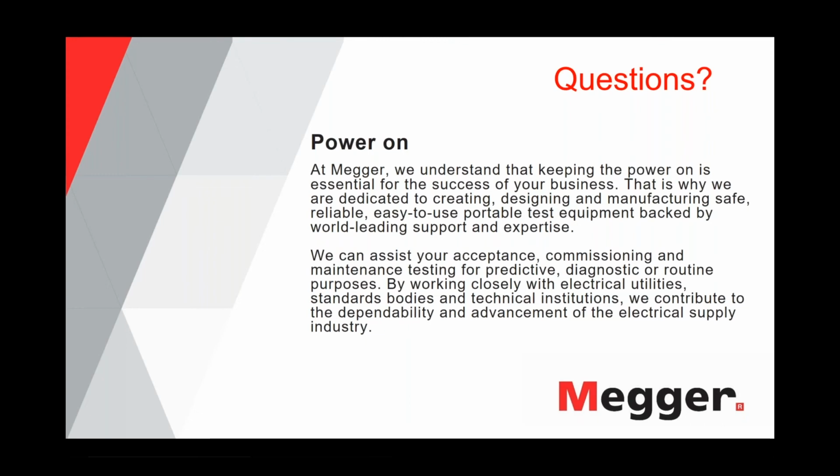Also, if you really want to dig very deep, they also have a substantial comment on tan delta on the background. And so the first thing, how to estimate the remaining life, is you have to get an idea how bad or how good your values are. And the standard is written, or the guide is written, in a way that you can compare your result immediately against these threshold values, without having to do any trending for 20 years before.